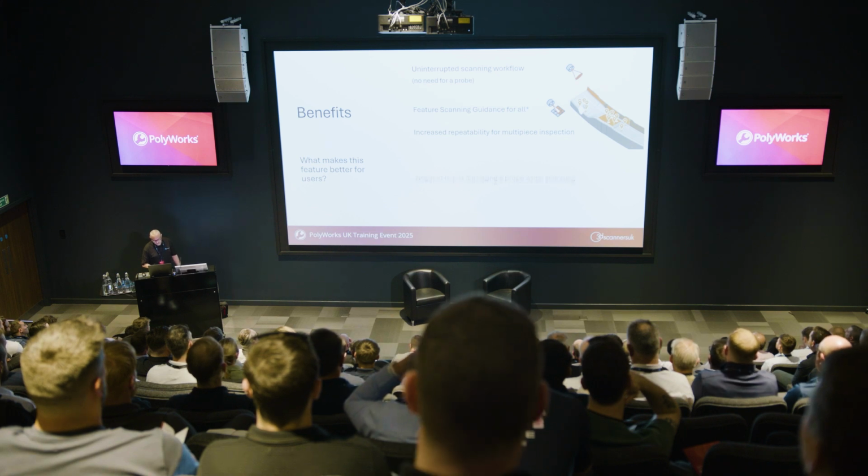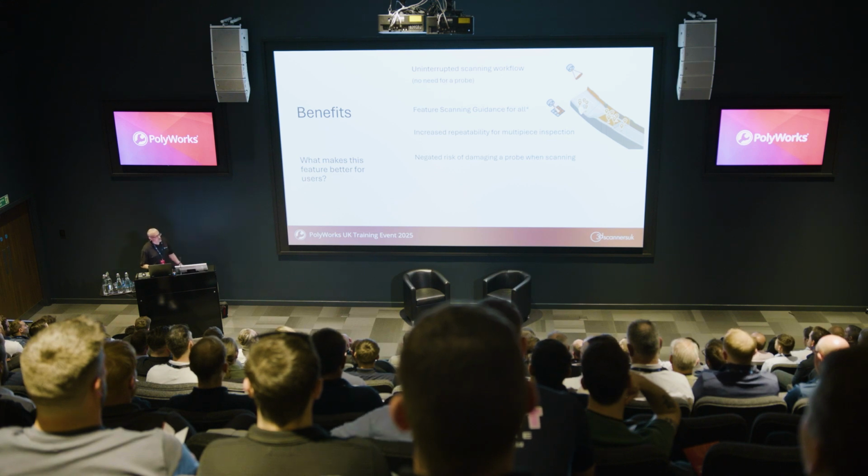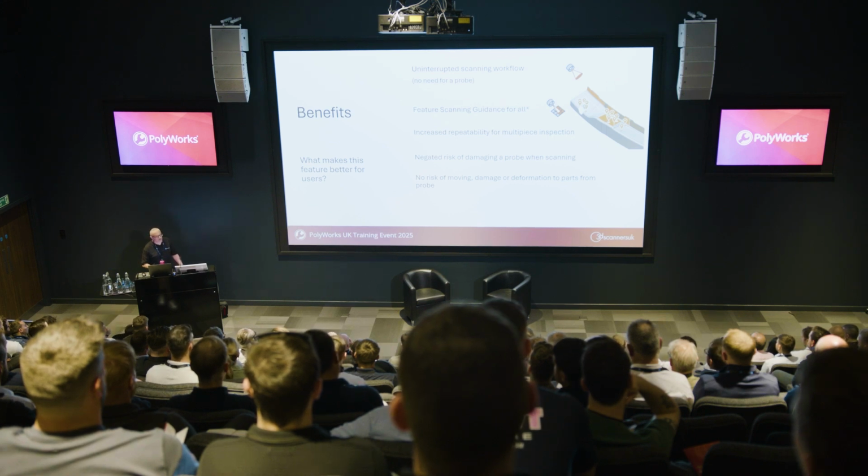And then there's some other things, so negated risk of damage of probe when scanning. Quite often, especially if you've got extended probes on and things, it's quite easy to knock the part as you go past with the probe. No risk of moving the part, damaging the parts or deformation to it from the probe. So if we've got a finished part that's been painted or polished, we don't necessarily want to touch that with a physical probe.